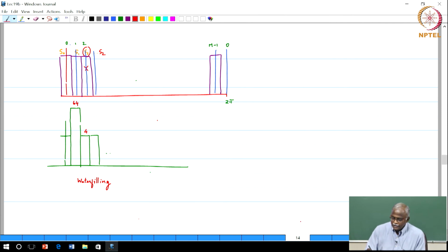Okay, so basically if you have a sequence of bits that you want to transmit, the modulation method says combine them into sets. If you combine 3 bits, then you will have 8 values. Let me take 4 bits, it is easier. Then I will have 16 possible values, and the possible symbols that I will transmit are one of these 16 QAM symbols, quadrature amplitude modulated symbols.